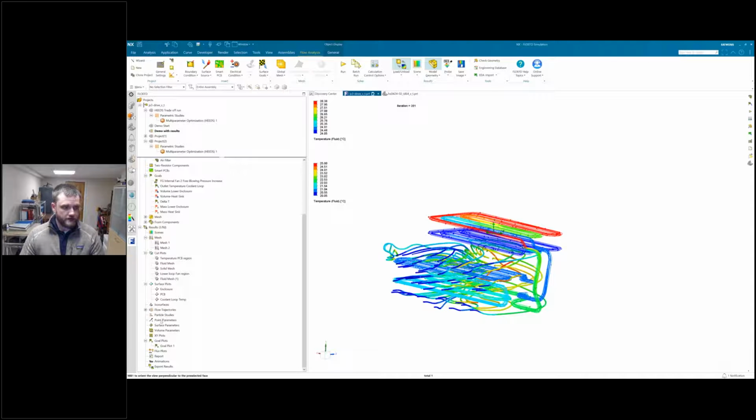And we have some other things. We can do particle studies, we can do point parameters, we can look at surfaces. We can do XY plots. Say you want to look at pressure drop at a certain location through a pipe, or temperature across a certain location with a specific sketch that you've defined, like a line. You can do that. We can also look at our goals that were defined for the solution.